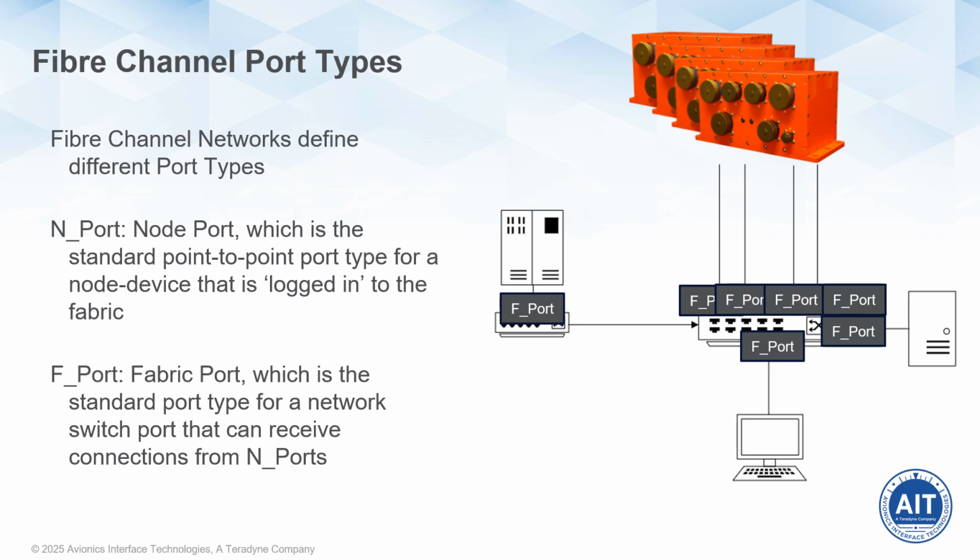For the port on the fabric side of each N port, there's going to be an F port, where F port stands for fabric port. And fabric ports actually start as a G port, where G stands for generic, so generic port. G ports could also be GL ports, where a GL refers to a generic loop capable port.